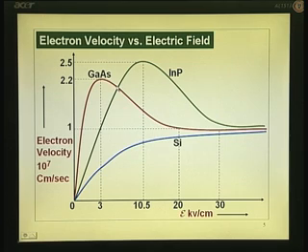This makes a lot of difference for the electrical properties of the two materials. Indium phosphide band gap is 1.43, but the delta E gap between the upper valley and lower valley is 0.53 as compared to 0.36 here. So, the transfer takes place at about 10.5 kilovolts per centimeter, from the lower valley to upper valley. That means higher field.